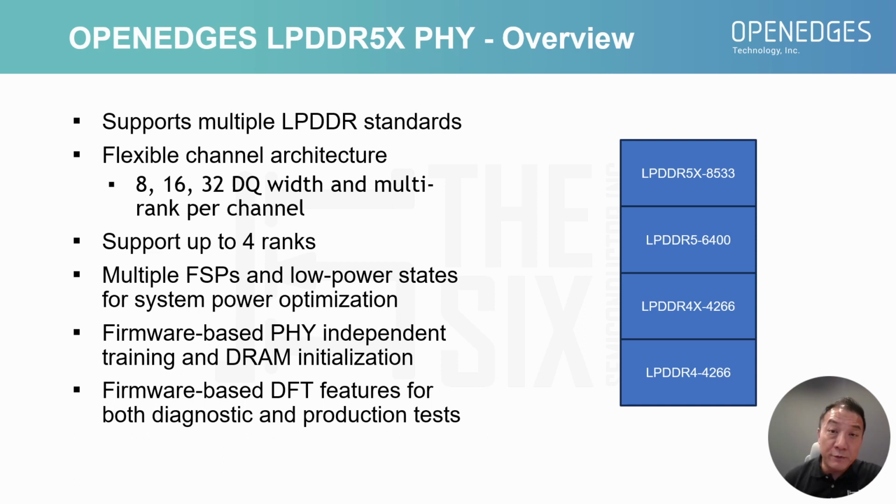The PHY has a built-in microcontroller, which I'll go into in a bit more detail in the next few slides. And with this, we have firmware-based PHY independent training and DRAM initialization, which does not require involvement from the memory controller at all. For production tests and diagnostics, different firmware can be loaded to exercise the PHY differently from its normal mode of operation.